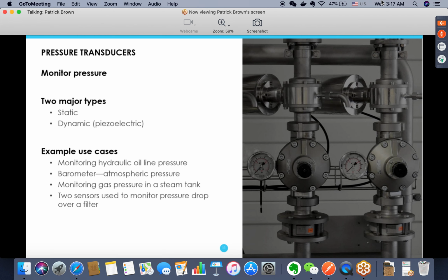However, the dynamic one cannot measure a static pressure head. A piezoelectric crystal requires a constant acceleration or deceleration, changing strain to create the charge. So if the pressure is rapidly moving, like pressure pulses are rapidly going through your pipe, you might want to use a dynamic pressure transducer to monitor those pulse train. However, one thing to note is that they are commonly zero-centered. So you have to know, like, is it 3,000? Even if it's 3,000 psi, it could read zero if it's static. The dynamic transducer will read a zero on a static pressure bed of 3,500 in most cases.